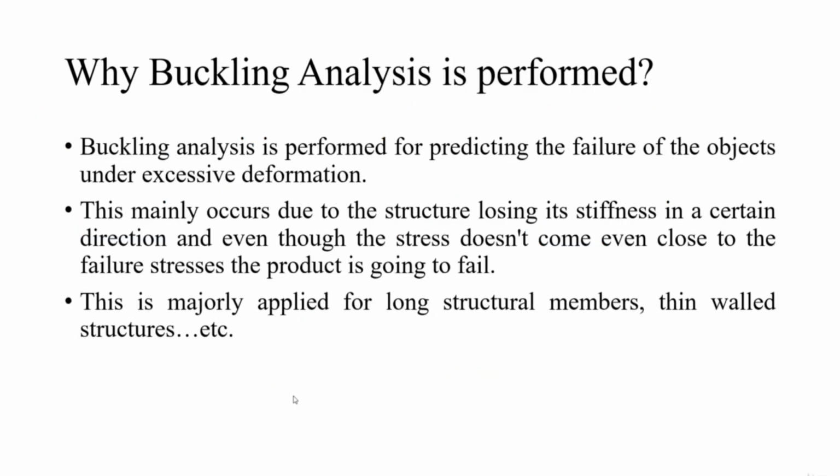So why is buckling analysis performed? Buckling analysis is performed to predict the failure of objects under excessive deformation. This mainly occurs due to the structure losing its stiffness in a certain direction, even though the stresses don't come even close to the failure stresses.